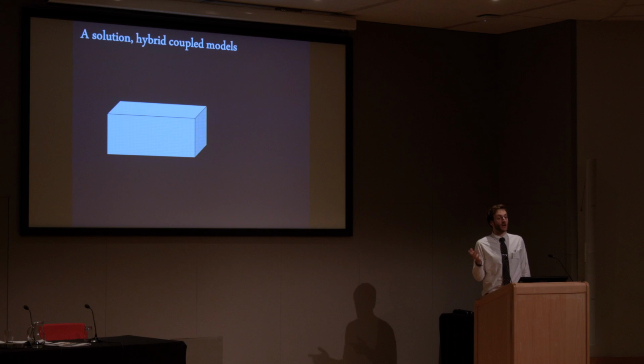So what's the potential solution? It is hybrid modeling, a smart way of modeling a building. We start off with our three-dimensional computational fluid dynamics model. In here, we're solving a form of the Navier-Stokes conservation equation. So we're conserving numerically mass and species, energy or enthalpy, momentum, and there's combustion modeling in there as well, and heat transfer modeling.